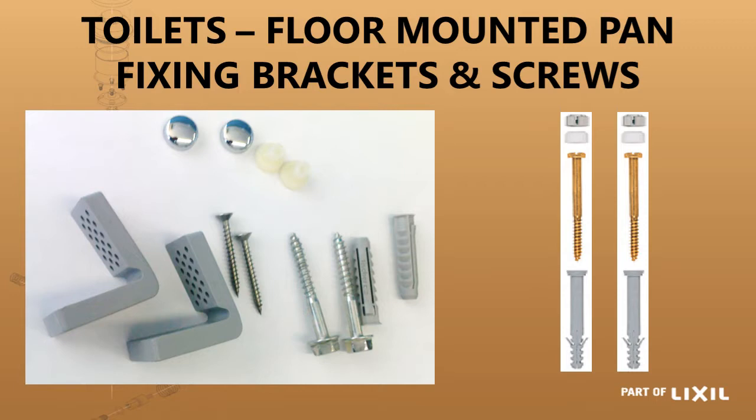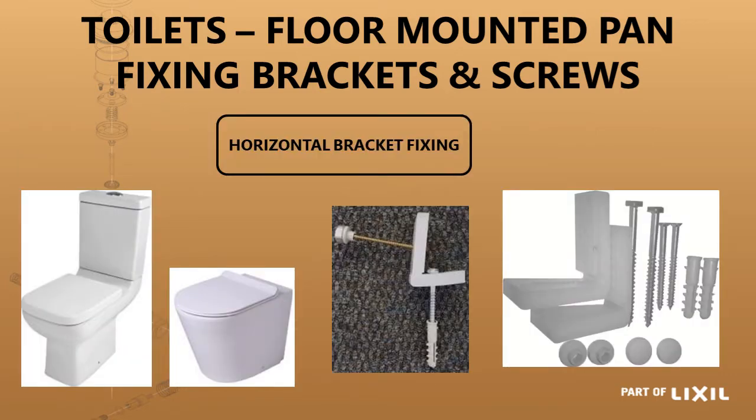Then the other one, you've got screws that just fix vertically down into the floor. The bulk of the toilets have got that screw hole on the side of the pan where you can secure the pan to the floor by using that screw. That is the pan where you've got the fixing hole, which is situated on the side of the foot, and you've got a horizontal screw that goes into the side of the foot, and that makes contact with one of those holes in the bracket, which is attached to the floor.